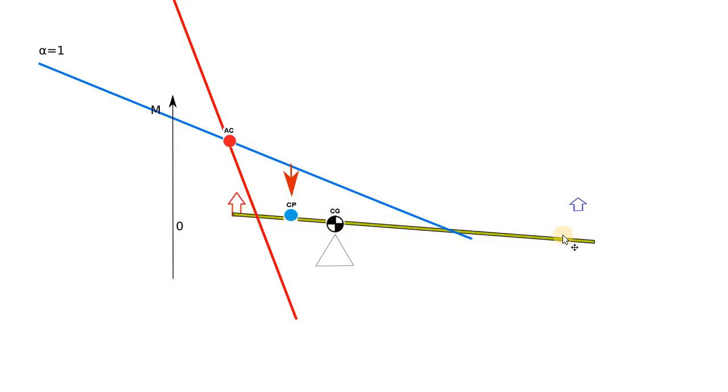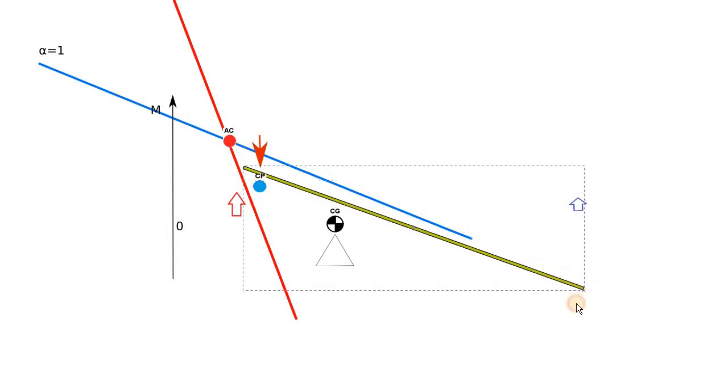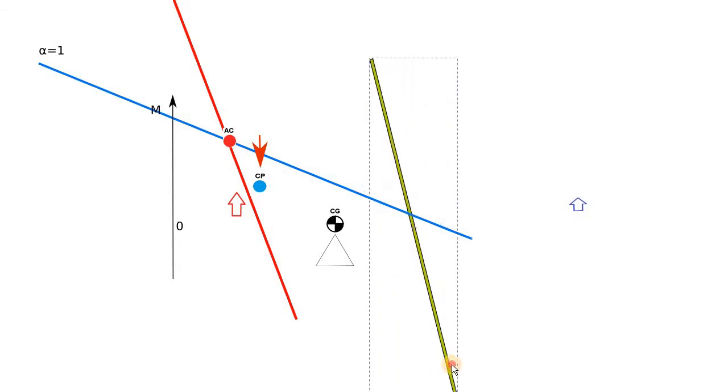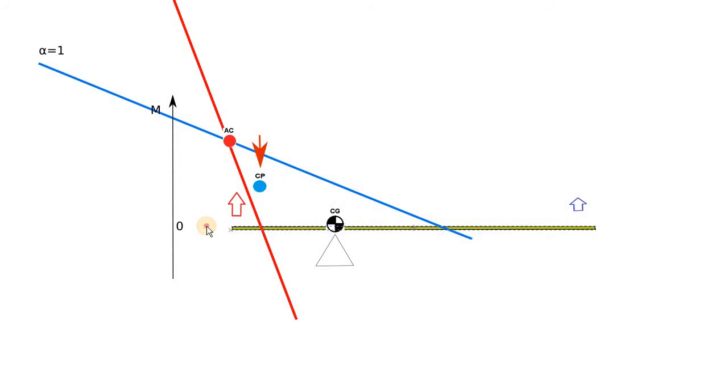And that means you're going to have the opposite effect, and the nose is going to be even higher. So we have even higher pitch up moment, and the center of pressure moving even closer to the higher alphas. As a result, we have the runaway condition, and this plane is not going to be stable. So we're going to have this situation eventually. But yes, the same actually applies for the opposite direction.